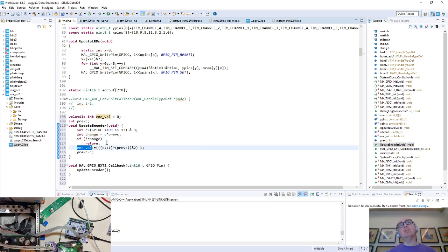And then we basically say, fine, if it's changed, then the change in the value is basically the XOR of the lower bit XORed with the previous higher bit. So you've got 2 bits. And basically, I'm only interested in the higher bit position. So the higher bit position from the previous frame, previous sample, and the lower bit shifted up into the higher bit of this sample. And basically, that circuit is the classic. You can do an encoder in an FPGA with a single XOR, basically. And so this is our XOR gate. This is our wiring. If I was doing this in FPGA, it's easy.